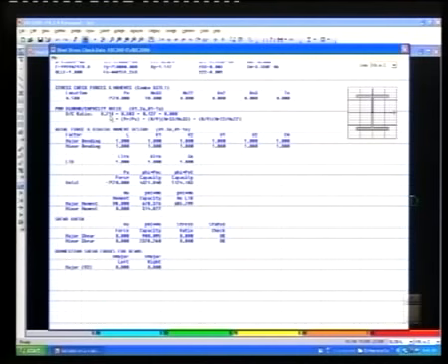We want to see where our problem is. Let us look at phi Mn and phi Mc. What is phi Mn and phi Mc in our calculation? It is 4332, which is right. Okay. And our capacity by phi Mn was 678, which is also right. But the ultimate bending moment, if you look at it, it's what? 90. What happens?